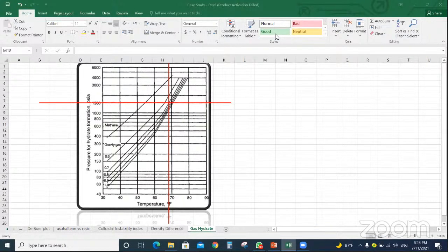Okay, we have a question. Does asphaltene in the reservoir itself prevent flow in the initial phase? If there is asphaltene in the reservoir, does it prevent the flow inside the reservoir? Yes, if the asphaltene is deposited in the reservoir, it will restrict the oil production. Why is the asphaltene deposited in the reservoir? Due to the injection of some light saturate components, like in the case of gas injection.